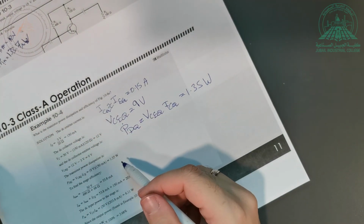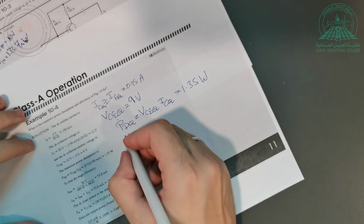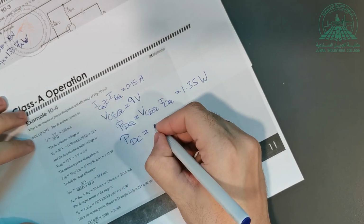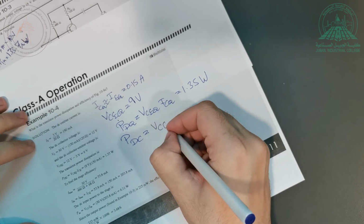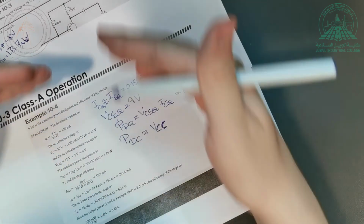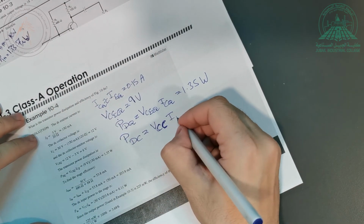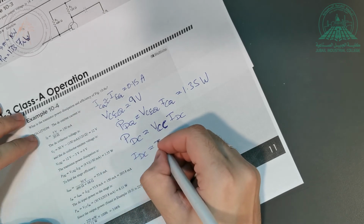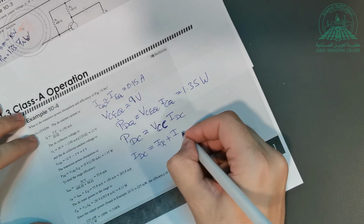Now if I want to find the PDC, PDC is equal to what? PDC is equal to VCC, the power coming from the power supply, multiplied by IDC. How much is IDC? It is equal to IR plus IC.